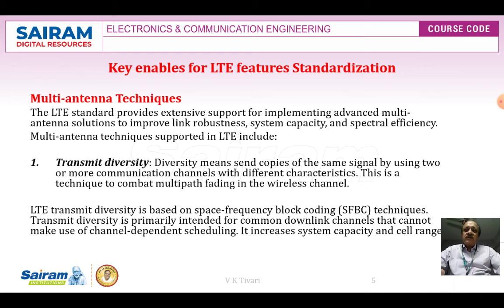LTE transmit diversity is based on space frequency block coding. We use the space frequency block coding technique in LTE transmit diversity. Transmit diversity is primarily intended for common downlink channels and cannot be used for channel dependent scheduling. It increases system capacity and cell range also.